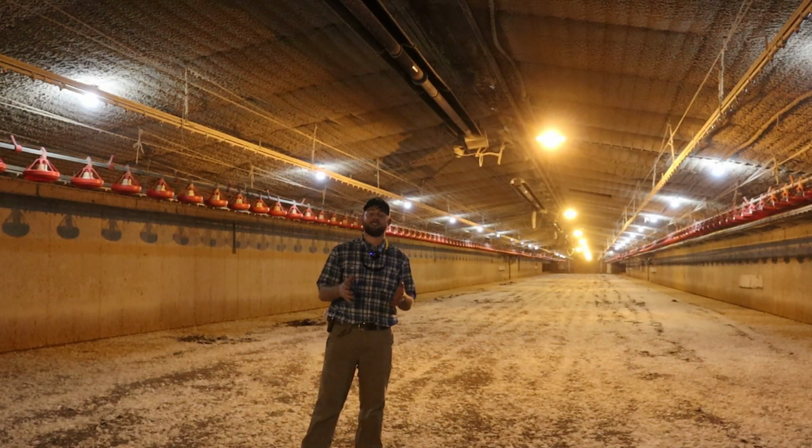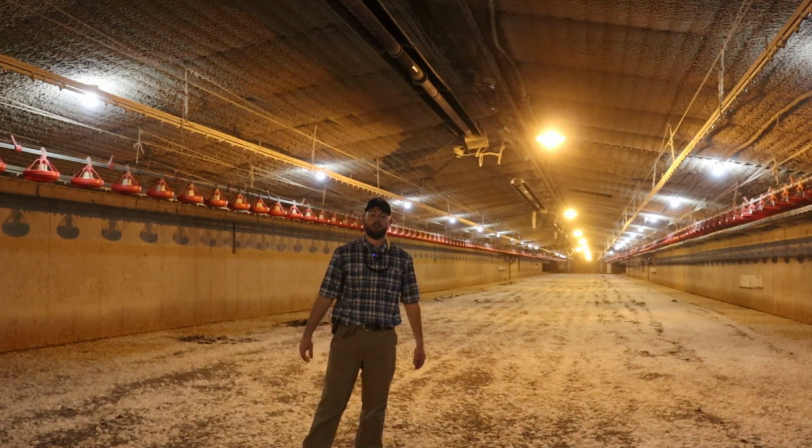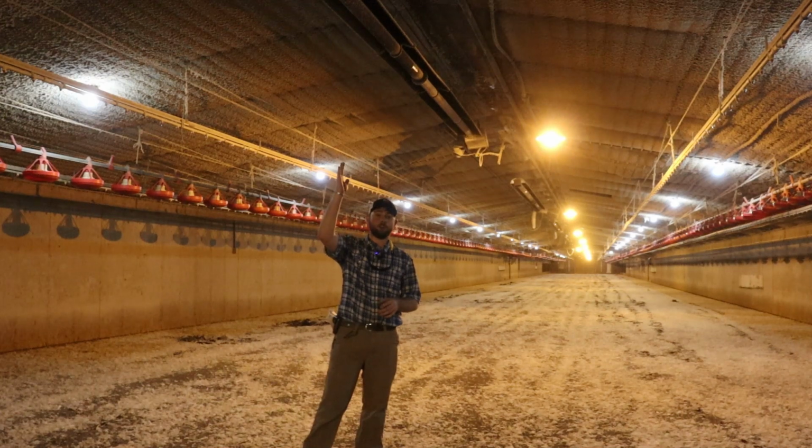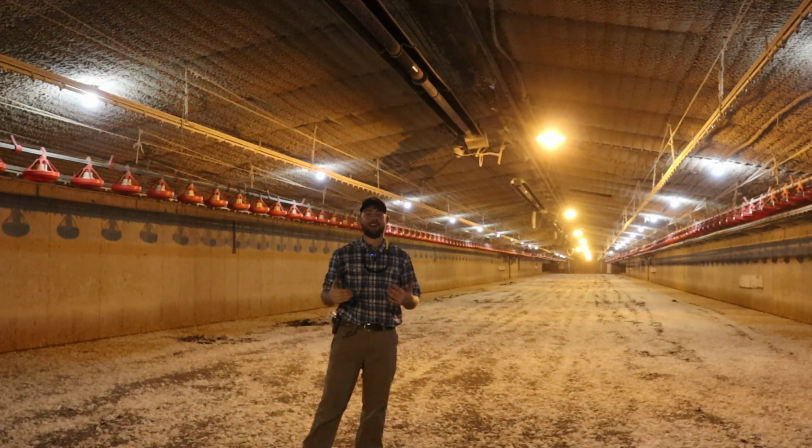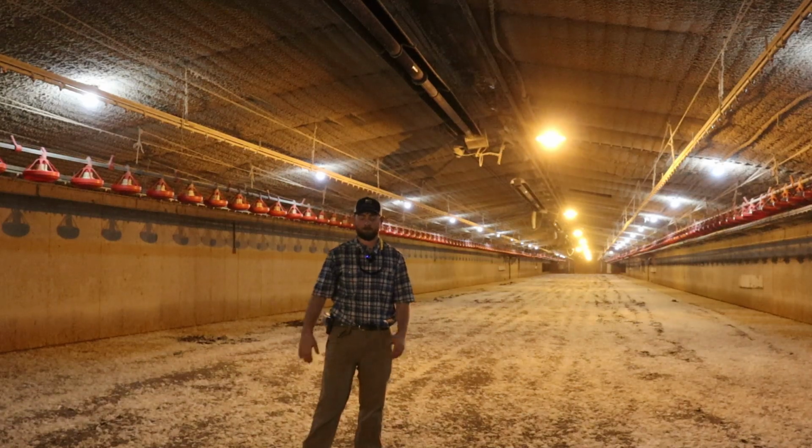Additionally, we can see fuel savings when we cut down our house leakage. That's because exterior wind conditions can bring fresh air into the house even when we're not trying to ventilate. It's going to force air through those holes and cracks, and then our heaters have to run to heat that air even though we were not trying to ventilate at this time. So the more we can cut down on leakage, we're going to see fuel and energy savings as well.